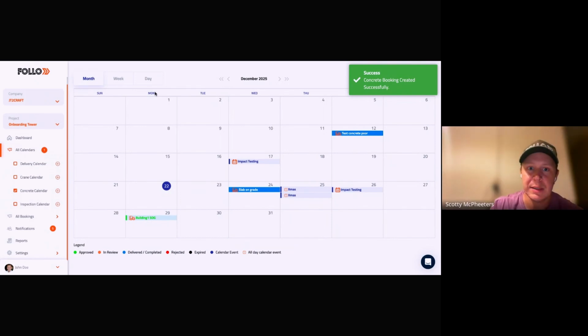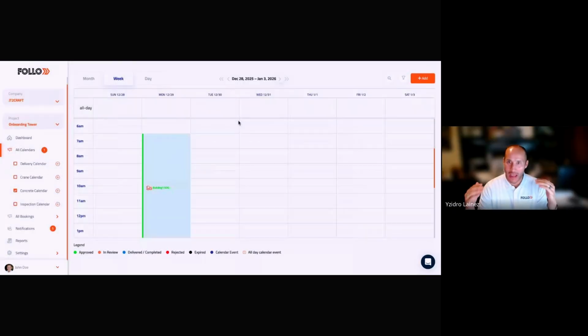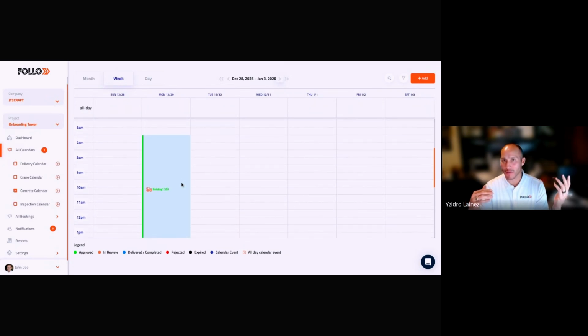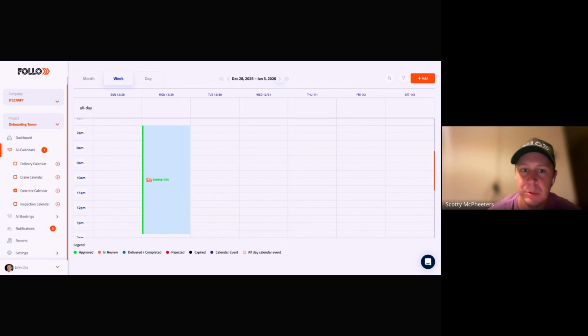That's exactly it. So if I go to checklist items, you've got a second gatekeeper making sure that it's going to pour, it's the right mix design, everything's lined up for it to be done at the right day and time. Exactly. And now whenever I try to book something else through this gate, someone's going to know there's a concrete pour, so don't bring anything else through that gate while I'm bringing concrete trucks in, because you're going to cause a traffic jam.